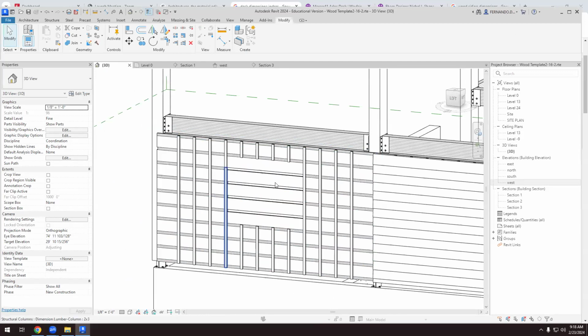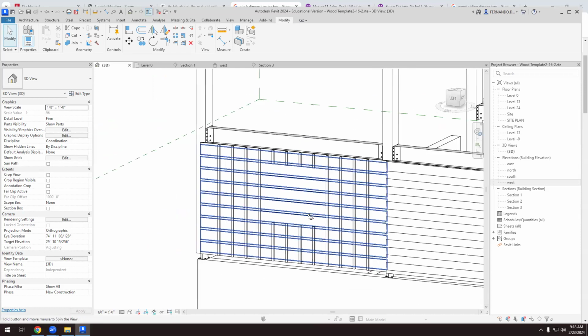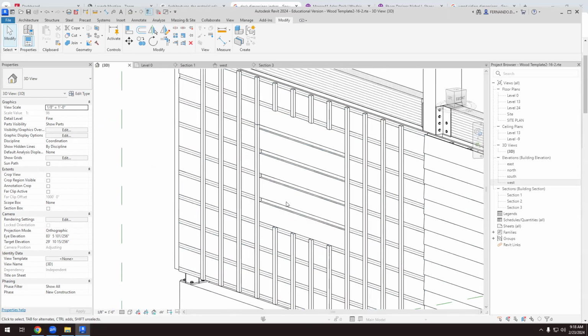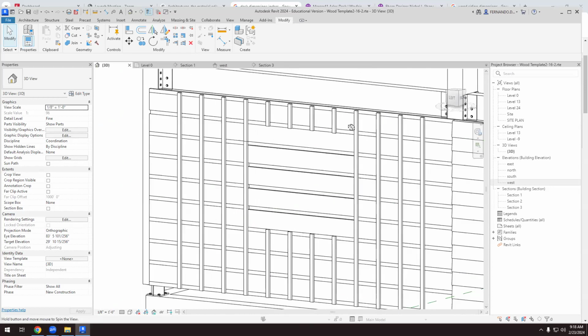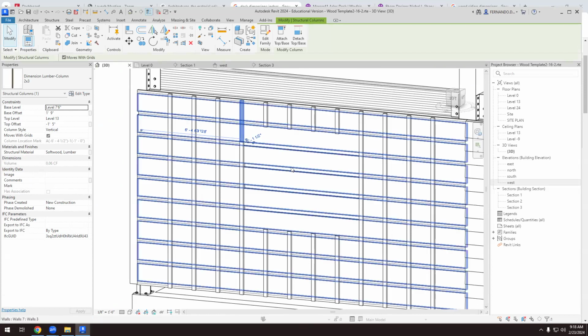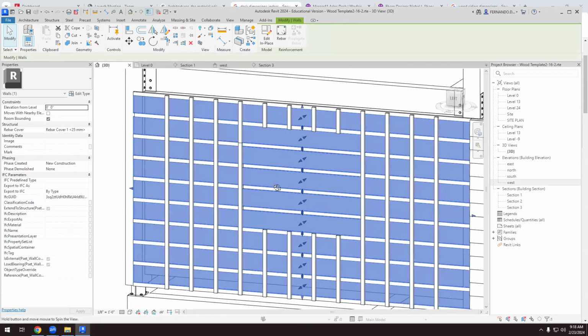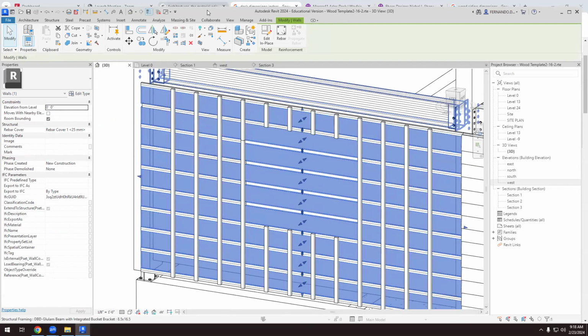So there are two different ways to cut or to open this rectangle here. The first: if I created this with beams, walls, columns, I can use the split. But if I have created something with a component model in place, then split doesn't work.